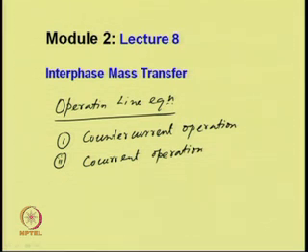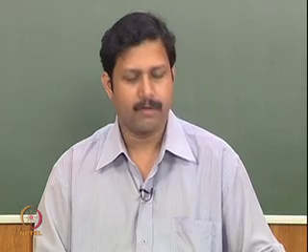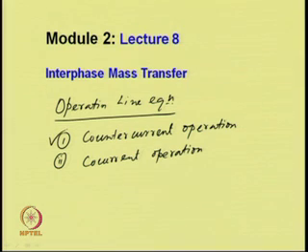And we have seen that among these two operations, counter current and co-current, the counter current is preferred because the average driving force for mass transfer in case of the counter current operation is more compared to the co-current operation. So, the counter current mode is favorable for mass transfer operations.